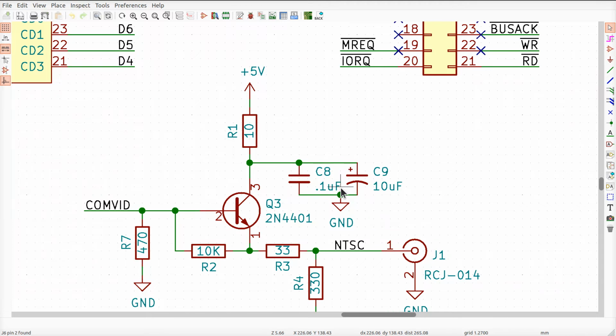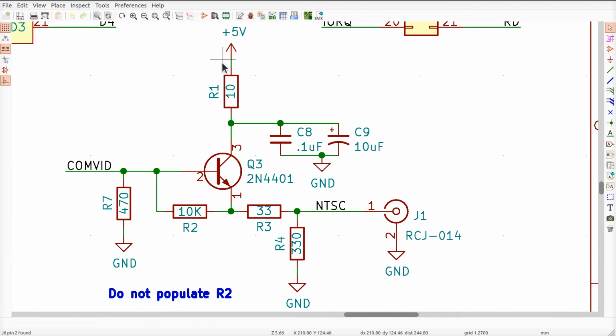Okay, but the idea and the intent, and I believe in the circuit where I saw someone did this, was that you need a fairly low resistance here. If you put some filter caps over here and they charge up through this resistance, and something over here draws a lot of current, it won't drain these capacitors back out. So having something like 10 or 50 ohms, or even 100 ohms, 100 would actually be way too much, because this whole thing, remember, needs to be able to supply the high voltage.